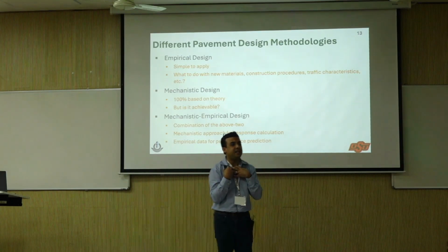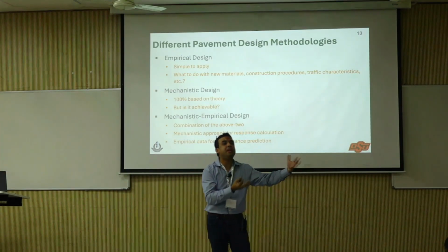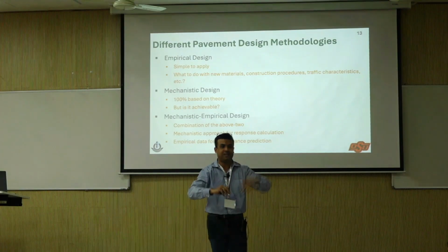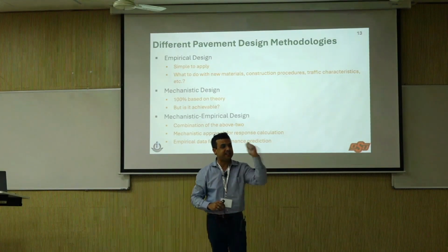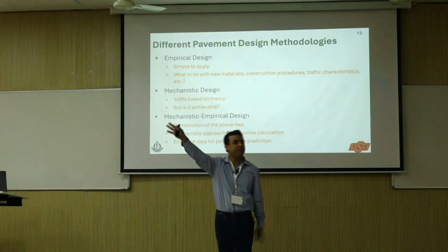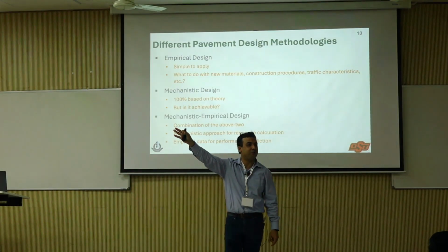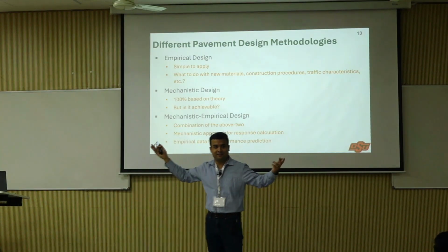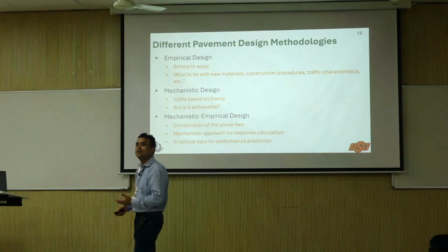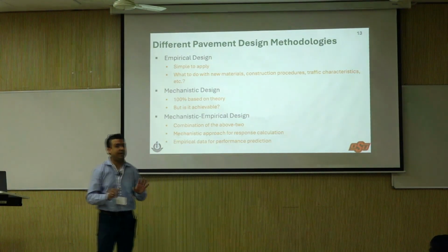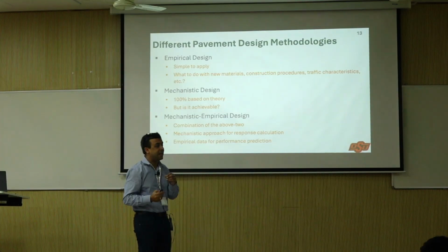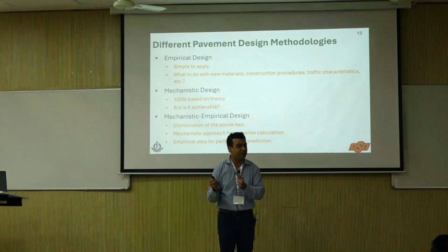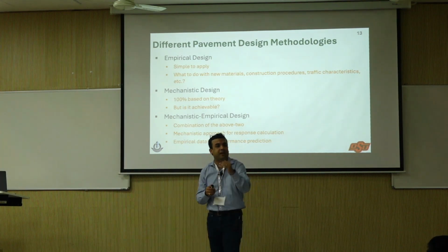Let's say I am a state DOT and I invested several million dollars today and over the next 5 years to establish my local calibration factors, and I'm like, bam, I got it. Next day my materials engineer says, I'm going to adopt balanced mix design, I'm moving away from Superpave. What does that do to my local calibration? It all goes down the drain, right? It's not that easy to do this. It's not that scientists are dumb or people have not paid enough attention. It is just that it's a very moving target.